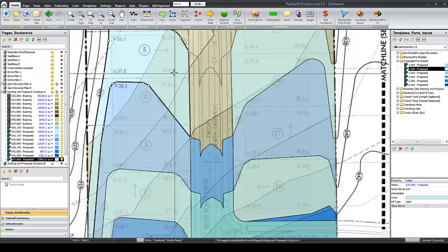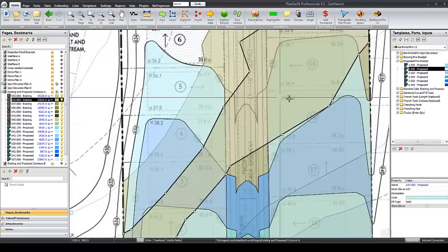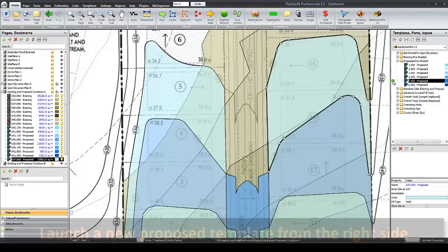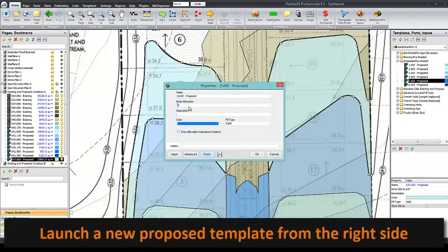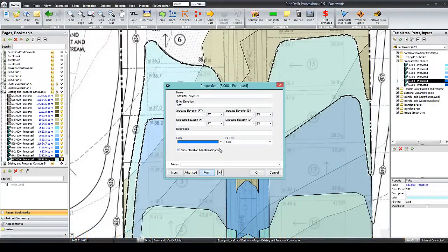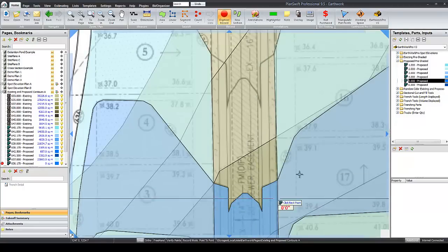So same thing here, I have 637 and 637, but instead of using those same sections for the roadway, I'm going to go back and dip into my well here and grab a new section, which I will call 637. Then I'll hit adjust elevations and decrease that like all the others by 10 inches and click OK, and then simply digitize in this area.